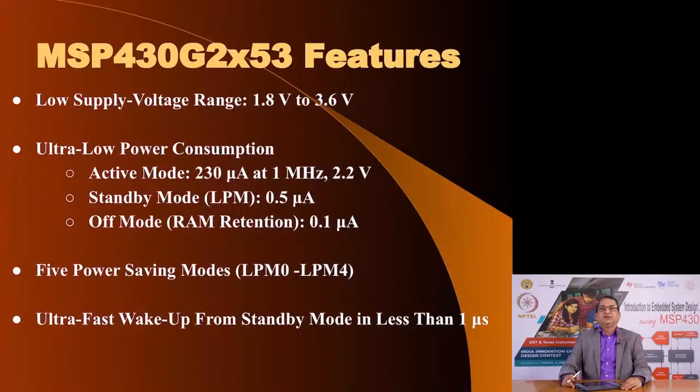These are the features. The supply voltage, unlike the microcontrollers of previous era where they would operate at standard 5 volts. You may also remember that TTL ICs, transistor logic ICs, operated at 5 volts, but as the frequency of operation increased, continuing to use a higher supply voltage led to higher power dissipation, and one way to reduce power dissipation would be to reduce the supply voltage.